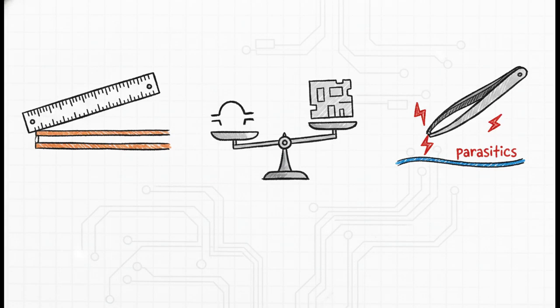Before a chip can actually be sent to the manufacturer, a massive milestone known as tape-out, it has to undergo rigorous physical verification techniques. First is the DRC, or Design Rule Check. This makes sure the physical layout doesn't violate any manufacturing rules, like ensuring two wires aren't placed so close together that they'll literally melt into each other during fabrication.